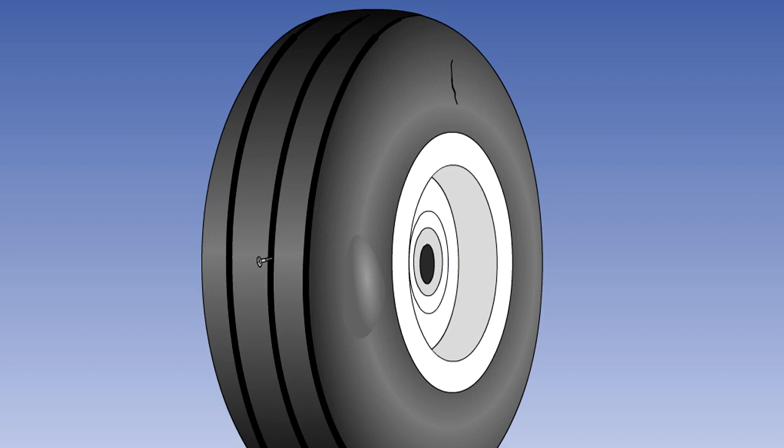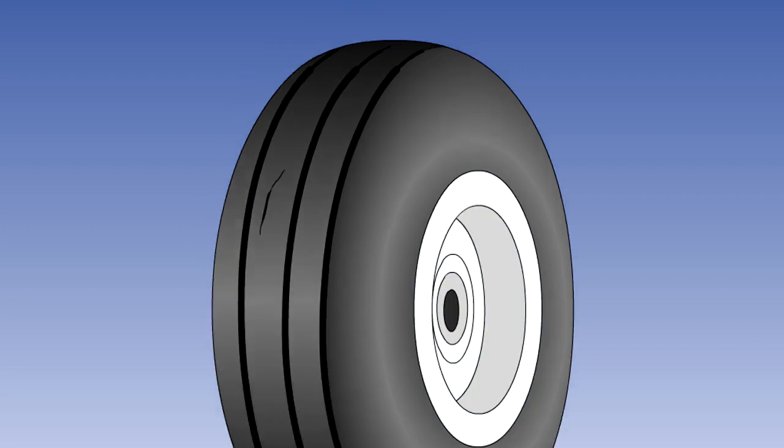During your pre-flight inspection, tyres must be examined for cuts, bulges, embedded stones, metal or glass, signs of wear, creep and local sponginess. Cuts in the tyre penetrating to the cords render the tyre unserviceable. The cords will be recognisable as pieces of white fibrous material embedded in the rubber of the tyre. Whether the tyre can be repaired or must be renewed is governed by the depth of the cut.